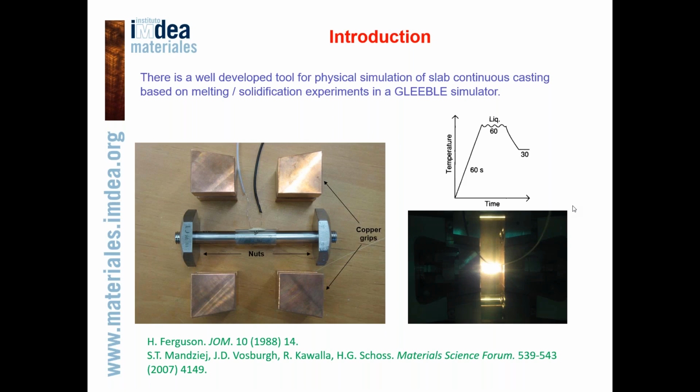I have also heard that some people apply compression once it's melted, I believe to make sure the molten material fills the cavity. Did you need to do that at all? Did you have voids in your melt? Yes, we did have some shrinkage porosity. We applied compression to compensate the thermal contraction during solidification and cooling.